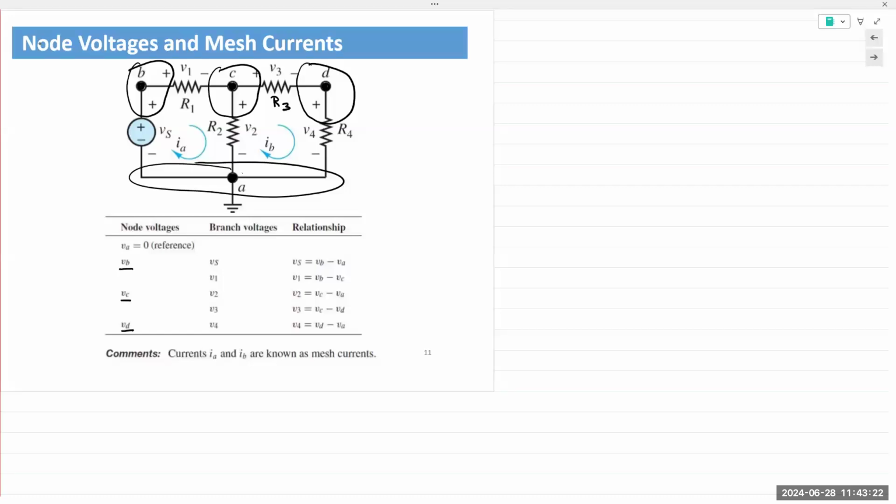It's not a two subscript notation. And that's because the second subscript is implied. Your baseline is implied. And that's what it means to measure a node voltage. You're measuring voltage at a point with your reference at a predetermined location. Remember, chapter 1 said we use a double subscript notation for voltages. The first subscript is the point of measurement. The second one is the point of reference.